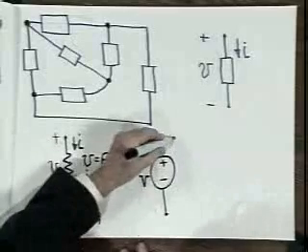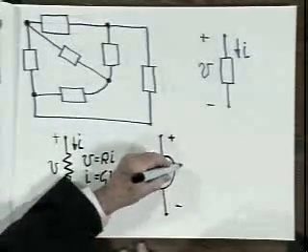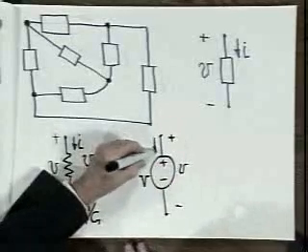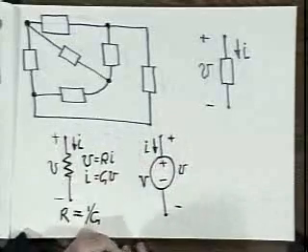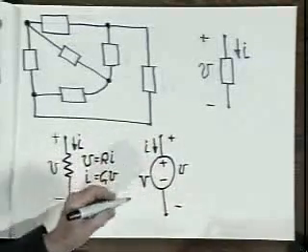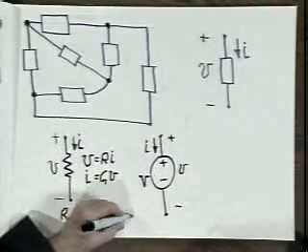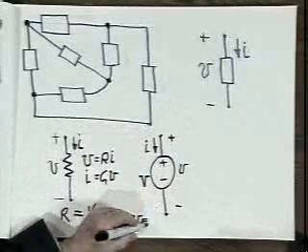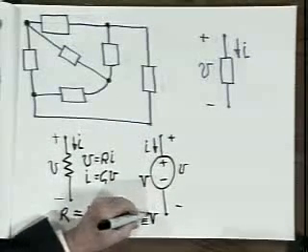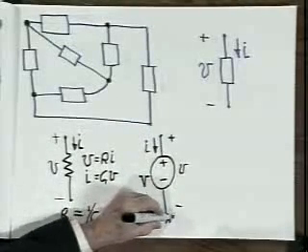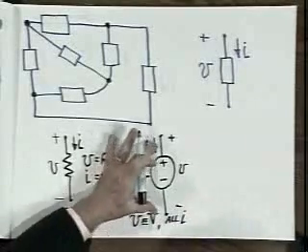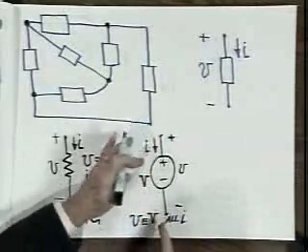And if we define a voltage for this voltage source and an associated current I, the relationship that goes with this is that the voltage V across the terminals is identically equal to capital V for all I. That is, the voltage source says that the voltage between these terminals is constrained to be a fixed number, V, no matter what the current is.